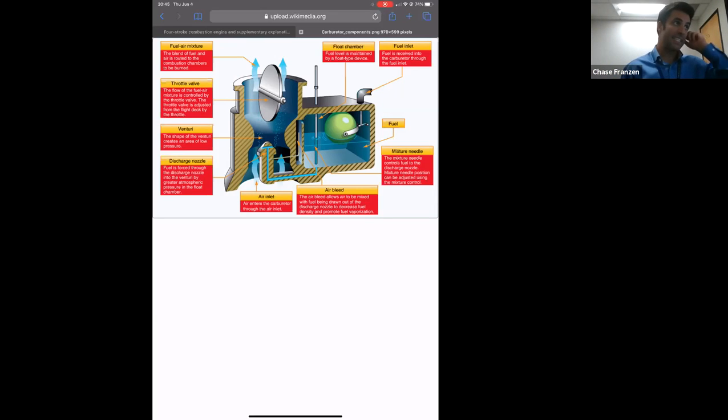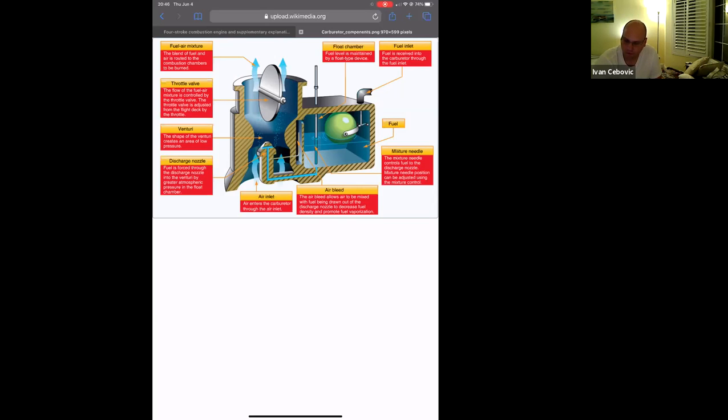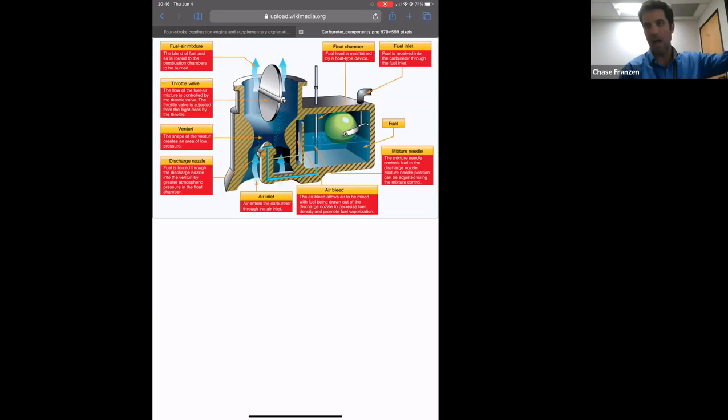To allow the gravity system to work, you have to have vents. In our aircraft, we've got 3 vents. Each fuel cap is vented, and then we've also got a vent in, oh gosh, which wing is it? I think it's the pilot side, right? Okay. We've got a vent on the pilot side behind the wing strut of the Cessna that blocks any crap from going into it. You do have a cross flow between the wings. So theoretically, one wing should be able to fuel the other wing and prevent imbalances.